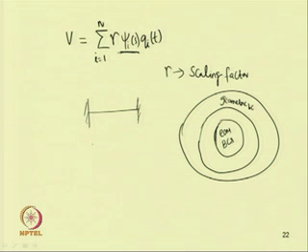But in case of this cantilever beam, at the left end we have the geometric boundary condition, but at the right end we have the force boundary condition. At the right end we have shear force and bending moment equal to 0. So, both shear force and bending moment are force boundary conditions.